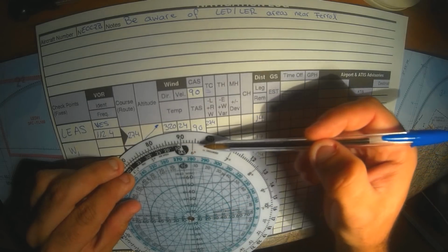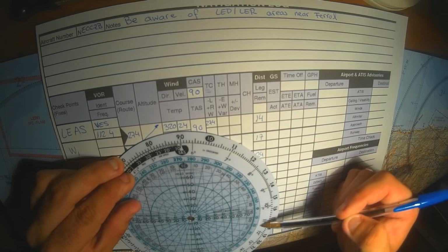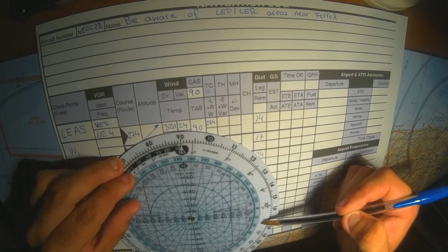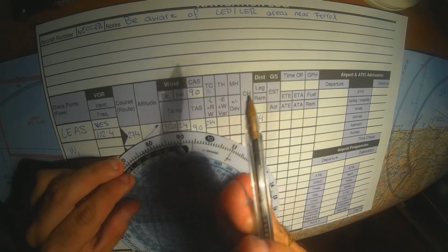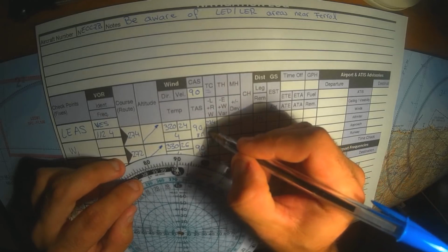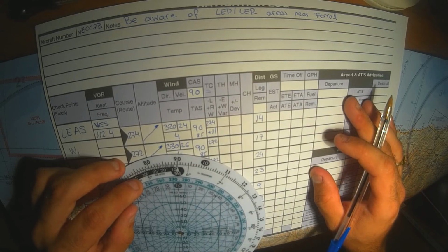This means our crosswind component is 17 knots, but we indeed want to know the angle of drift this wind is causing our aircraft, to compensate for it. We find 17 on the outer scale and see the angle below, 11 degrees of drift to be compensated into the direction of the wind. This actually is our true heading.